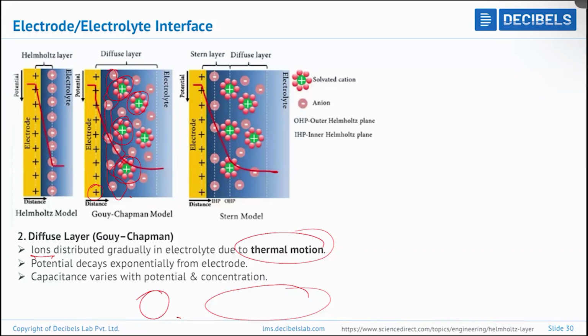That again depends on the crystal structure, which I have covered exclusively in the module 2 videos, on the crystal structures of lithium cobalt oxide and why the practical capacity is less. There is a liberation of oxygen if you remove more lithium, and there is a collapse of the crystal structure, and as a result it fails to give more cycle life and also leads to degradation. So obviously that capacity is calculated based on the SOC, the state of charge.